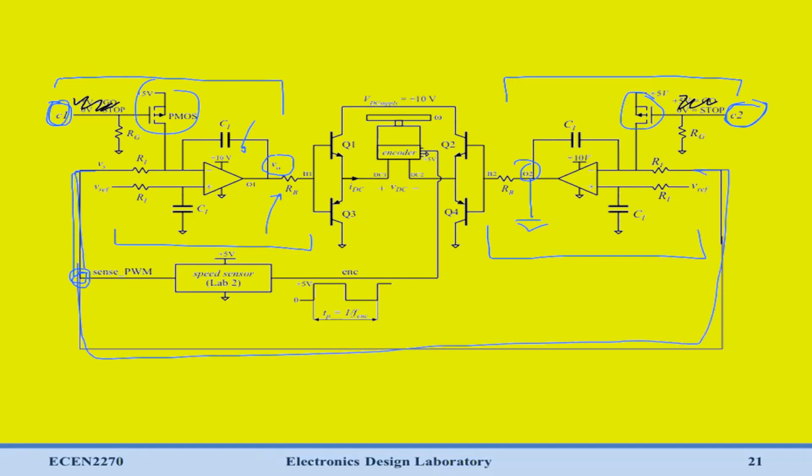So when you build this, you'll actually be building 2 separate feedback controllers. You'll have 2 separate PMOSs to switch one of them on and off, and you'll use these C1 and C2 inputs to control the direction of your motor. Now we can use the same speed sensor output for both of these. So Vs is going to go into both of these feedback loops.